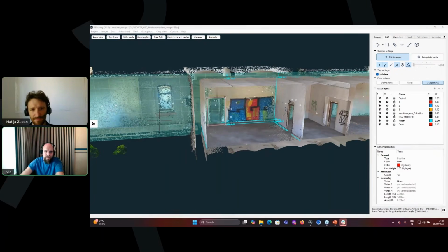Yeah, so actually for this project, we did not touch on ground control points, but when we were outside, we did place some ground control points and we measured them with the GPS just to make sure. But when we did the comparison in this case, the elevation difference between the model from the photogrammetry and with the SLAM device, I think it was within a few centimeters. So typically what we see, if you have a good RTK, there's about a centimeter or two accuracy offset between the measurements, which is what we usually expect from using GPS for georeferencing. But I would say that's a safe approach to go, to have a backup. Yes.